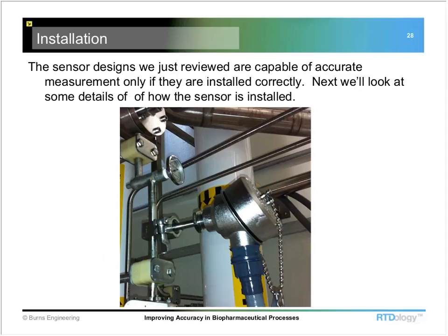Yeah, one more question had to do with the elbow well. Does an elbow well increase flow resistance significantly? The tubing is flared out around the thermal well portion of it, so the objective there was to not restrict the flow at all. The actual cross section of the tubing that's available for the flow does not change when it gets to that sensor. So typically we really wouldn't see any flow restriction there.